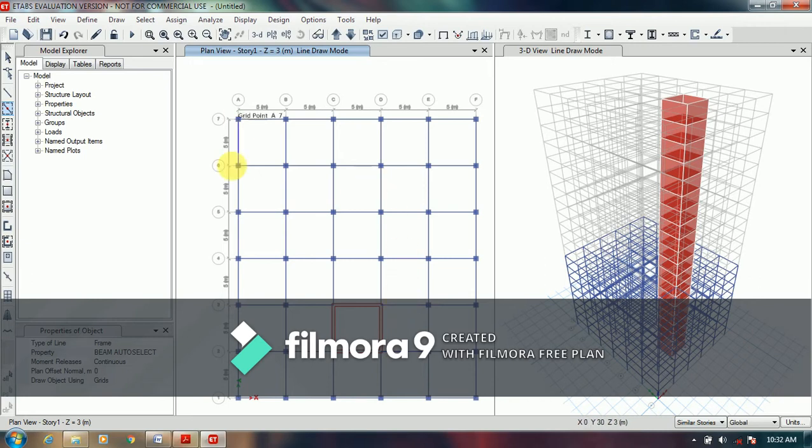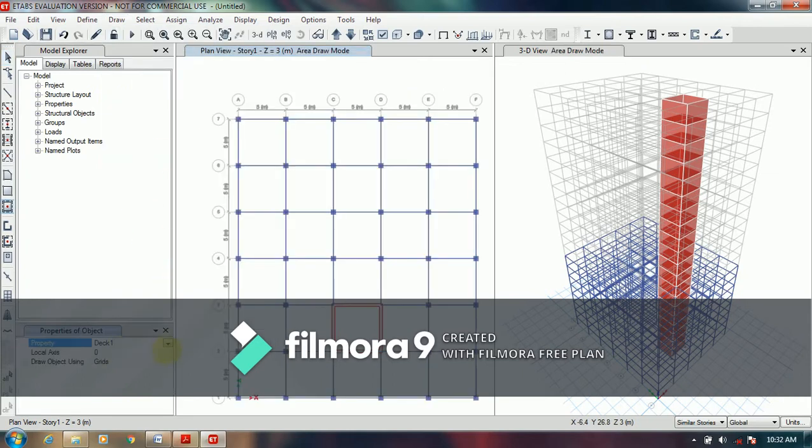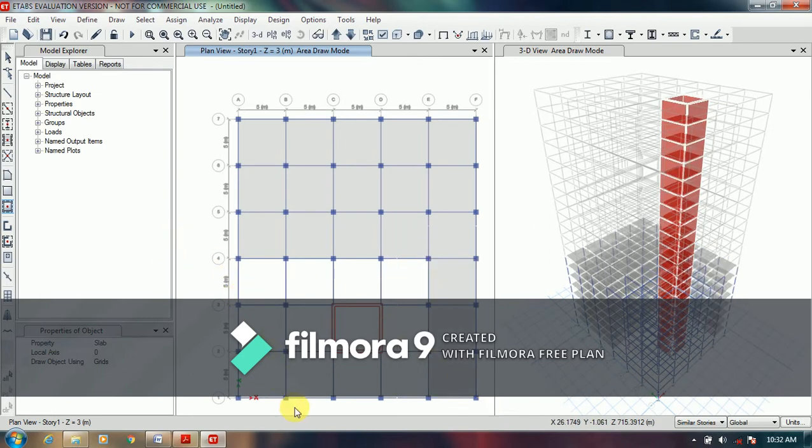Now we have drawn all the columns and beams. So now it's time to draw the slab. So again go to draw. Now draw floor wall object. Quick draw floor wall. Now again change the property to slab as we have defined it as slab. Now select the area where we have to draw the slab. Now choose the slab near shear wall one by one, as shear wall does not have slab.